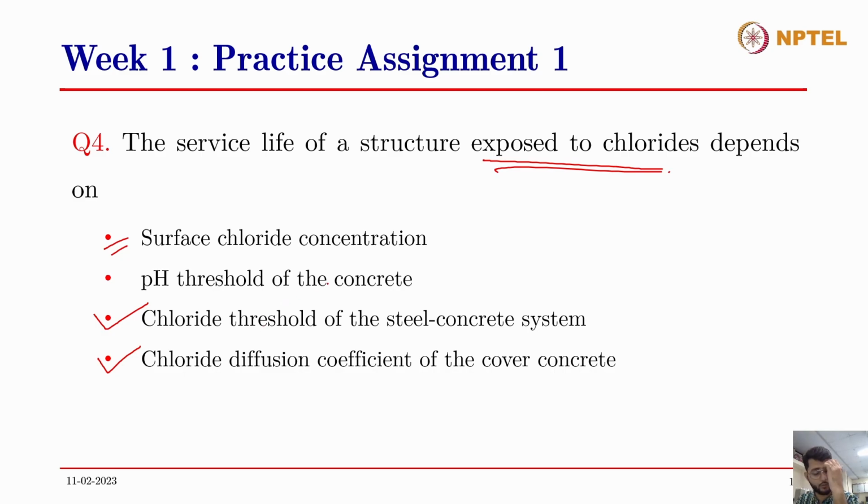Let's go one by one. Chloride diffusion coefficient of the cover concrete: how does it affect the service life of a structure exposed to chlorides? In case the diffusion coefficient is high, then related to the time factor, there will be more chlorides after a certain time, because the diffusion coefficient has something to do with the element of time.